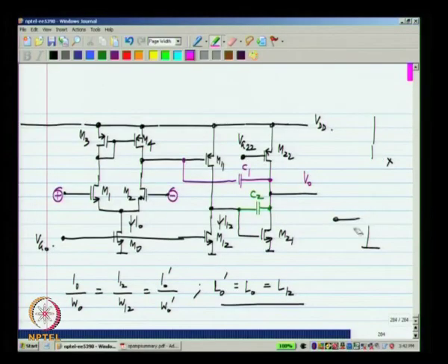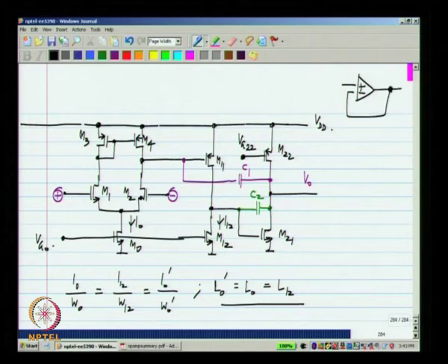Okay. Now, in the op amp, the way we have drawn it, the current sources are going directly into the drain and nowhere else. Obviously, as you know, the op amp can be used only inside a feedback loop. Okay. Let me again for illustration consider a unity gain follower. Okay. What happens in that case? I will have a connection from there to there, and the plus input, let us say, is biased at some V bias. Okay.